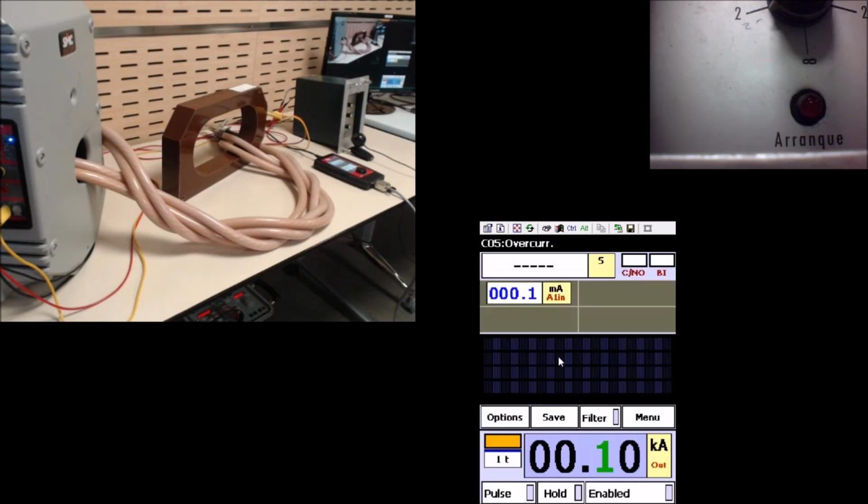So now you see we have an additional meter here, and this is measuring the current across the secondary output of the CT. Any injection that I do will show the secondary value, the conversion made by the CT, in this small display here. And here you will see the time for tripping.